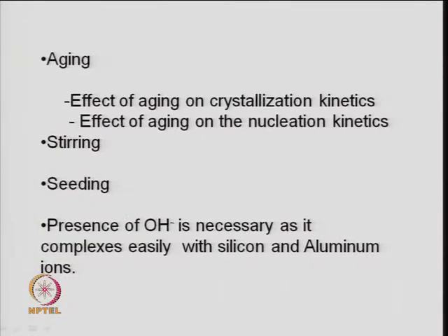So, aging, the effect of aging on crystallization kinetics. It can be a separate chapter, one can do R&D on this: what type of zeolites are desired and what happens to the structure of the zeolite after aging, and how the rate of crystallization changes with the time of aging, temperature, and time, and look at the growth of the crystal, and the effect of aging on nucleation kinetics. These are important, because your final crystal size or type of crystal depends on this aging, its temperature and time.